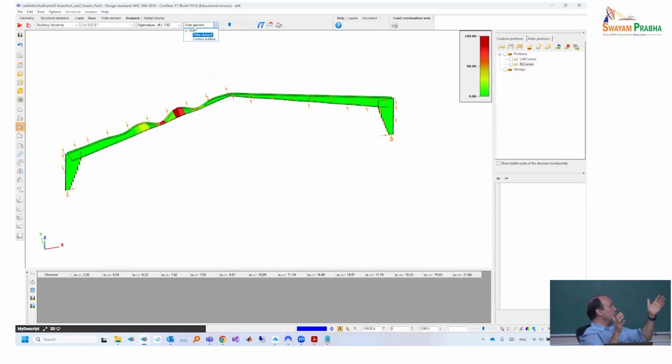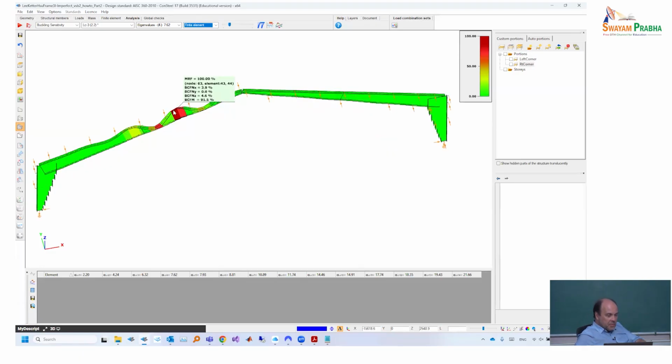So to accumulate all these energies member by member, and then we show them not by finite element but by member distribution. And then the 100% will be the maximum value, and proportionally all the others the lower value. So for example, what we can see from this mode, where visibly the biggest deformation was here, if we take also into account the section there, and which is stiffness, and we calculate deformation energies, from this concept it is also visible that these are the most exposed locations.